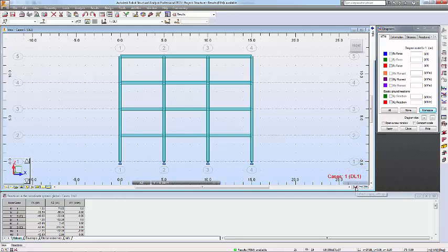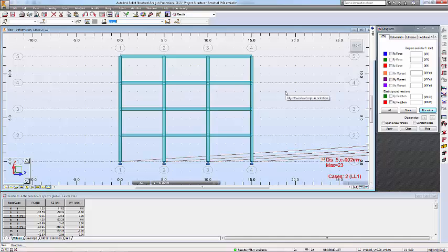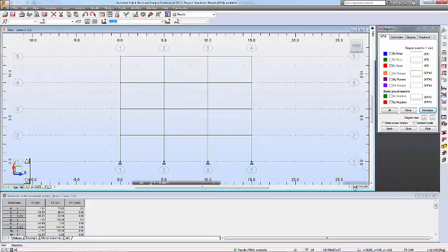So if you want to see the deformation, you can click on this one. So that's the deformation, but pay attention to this one. This is only for the dead load. Okay, so dead load they have a different settlement, and you may want to have a look at live load. So that's the loading you have in horizontal direction, and that seems too much. So we can set the display value by clicking on this one. Oh, sorry, that was this one.